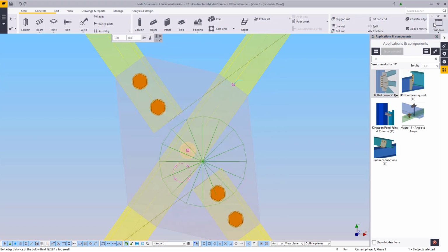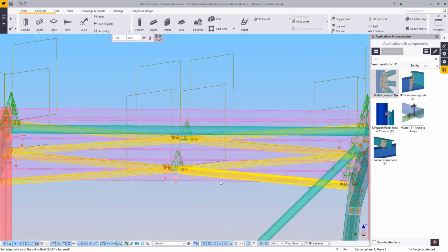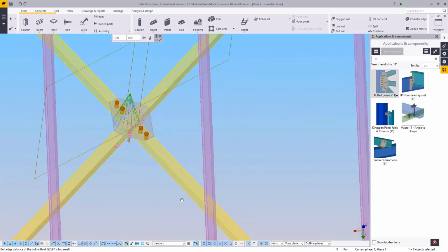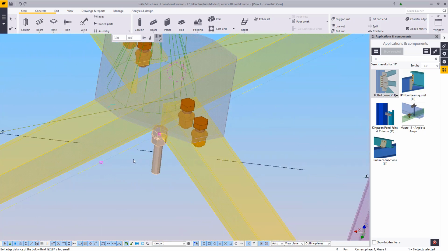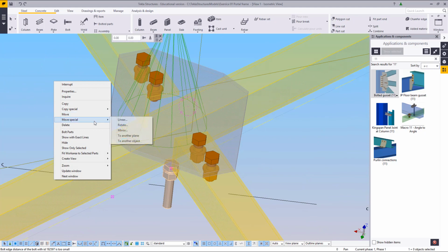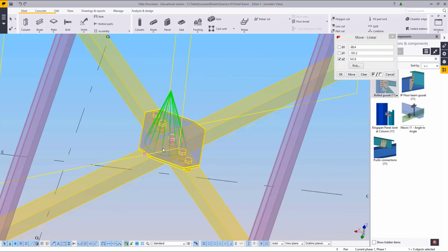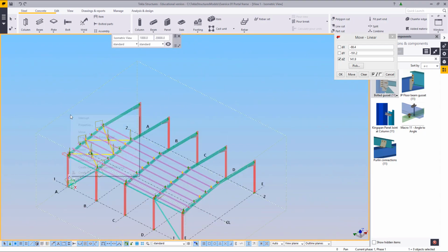If you do put it in on that view, you'll find that the bolt that you put in right under here does not exactly go into the gusset, in which case, like we did with the lines, we will need to move it up by only the Z-axis. That should be it for bed bracing.